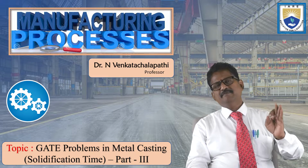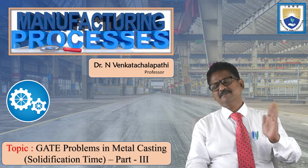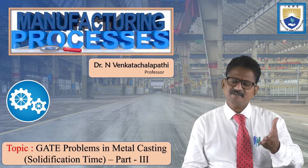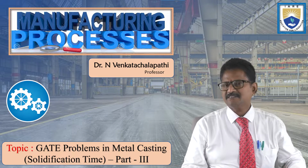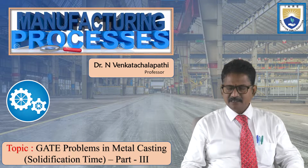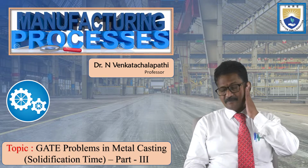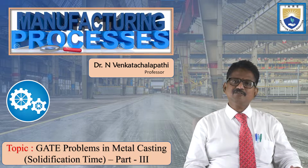Before applying the shrinkage allowance, what will be the dimension, and after applying it? Similarly, before applying the draft allowance, what will be the size, and after applying the draft allowance, what will be the size, can be determined easily. So in this part 3, another important problem I'm going to discuss clearly is how to solve the solidification time.